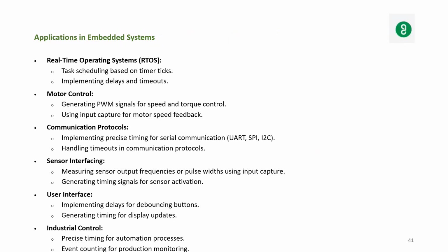Communication protocols: implementing precise timing for serial communication such as UART, SPI, I2C, and handling timeouts in communication protocols. Sensor interfacing: measuring sensor output frequency or pulse width using input capture, and generating timing signals for sensor activation.